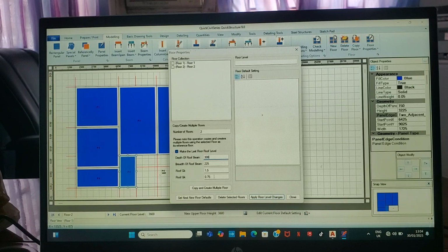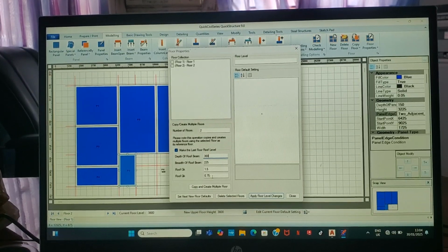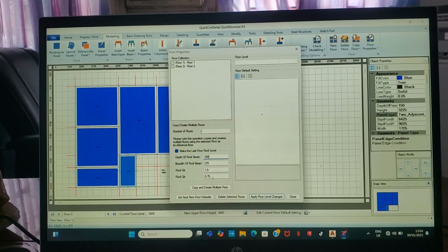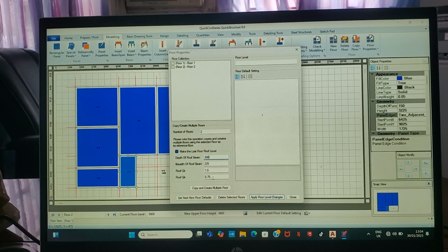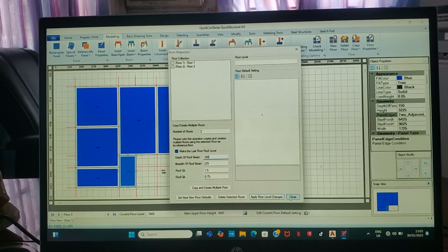Roof QK, the live load because of dust, snow in the morning, is 0.75. Or if you are in a country where snow falls a lot, there is a live load on that. You can get that in the BS code. All right, so let's continue.